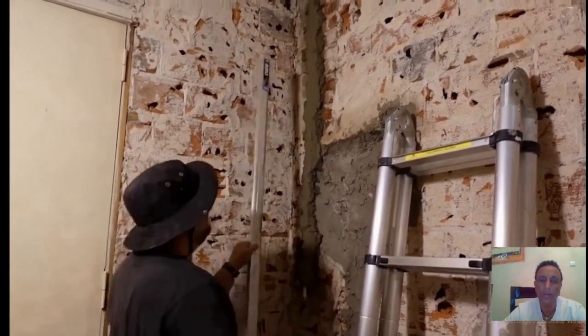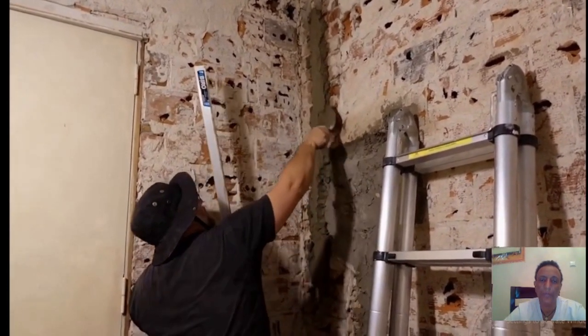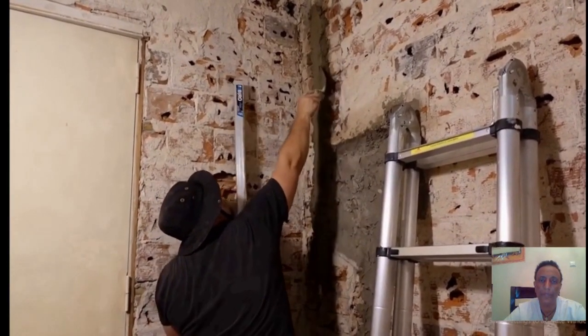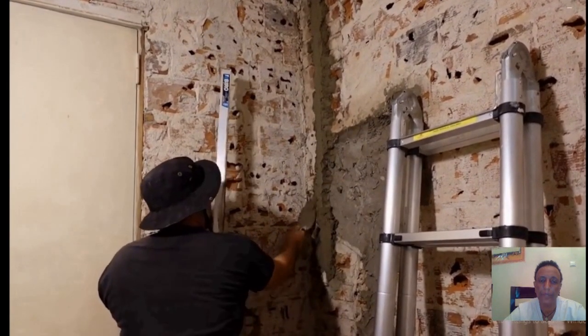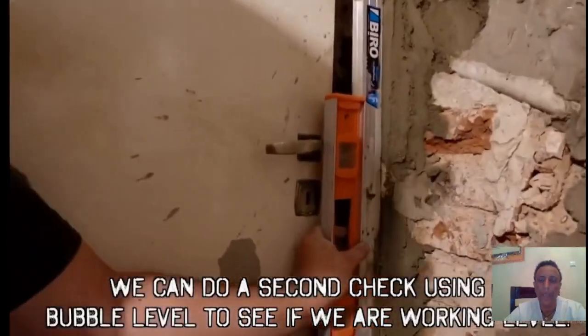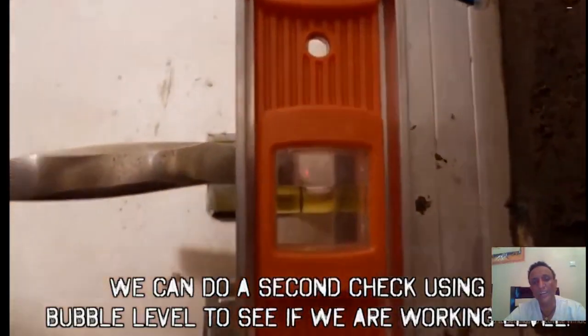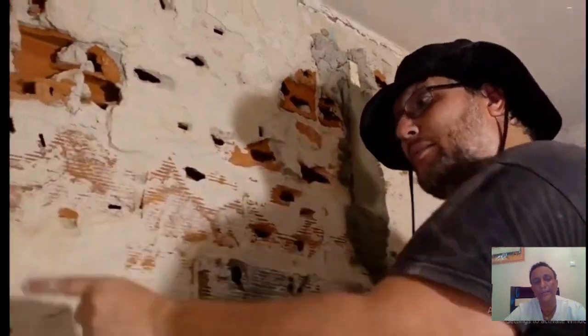Okay, now it seems good. And check the verticality of the strip. This is a spirit level. The water level should be at the center of the spirit level. If it is good, the work is correct.